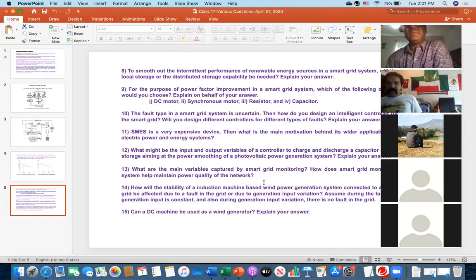So this means that your input power is varying, that is coming from the photovoltaic system. Your controller has fixed power, which is the demand or the requirement of the customers. So your controller will look at the measured power, and then based on the power, it will create an appropriate duty cycle to maintain the charge and discharge. Then the voltage source and transformer, finally it is connected to the grid. So the main thing is choosing the appropriate input variable and then the output variable.